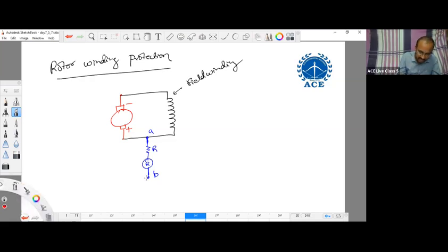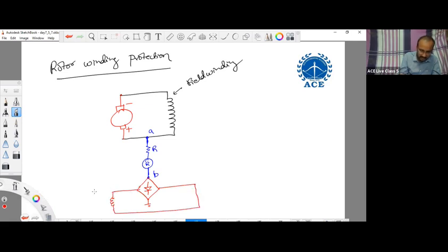We will use a DC rectifier circuit here, a full bridge rectifier circuit. How do you construct it? What are the inputs for this DC rectifier? An AC value is required, no? So we will excite the AC source, and this is a DC rectifier circuit. By using this rectifier, we will initially maintain the potentials at nodes A and B the same. Initially, VA equals VB.